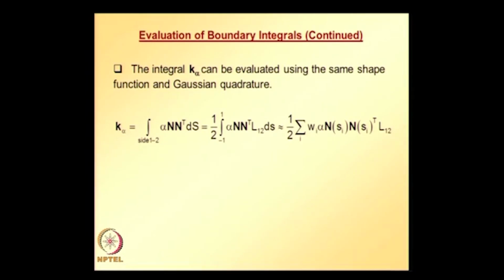and the procedure is the same if a natural boundary condition is specified along any other edges or sides. The only difference is that different shape functions are 0 along different sides. I think you agree with me on that, that is, different shape functions are going to be 0 along different edges. So, we need to take care of that when we are evaluating these integrals, and we need to be careful along which side we want to evaluate.